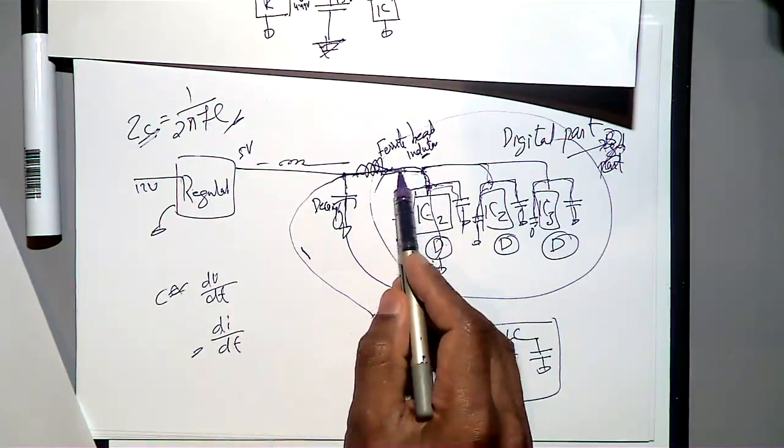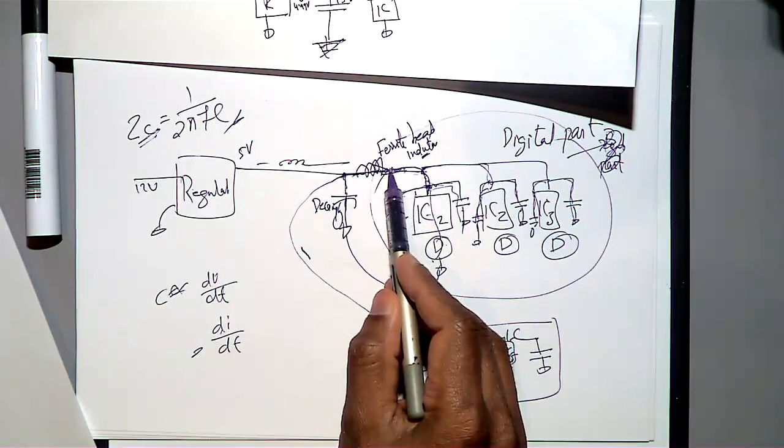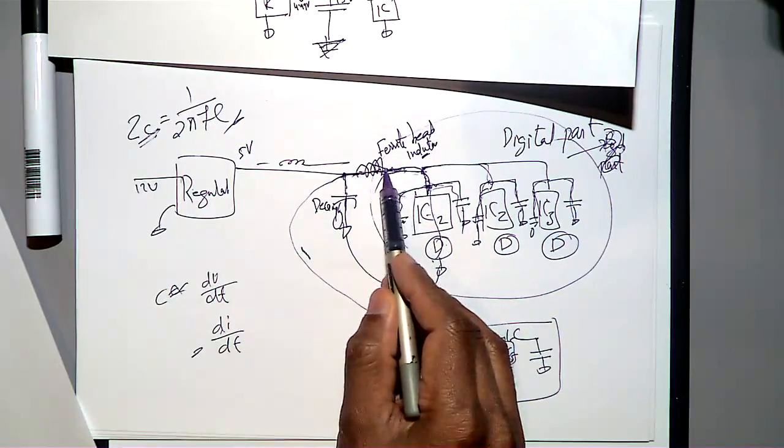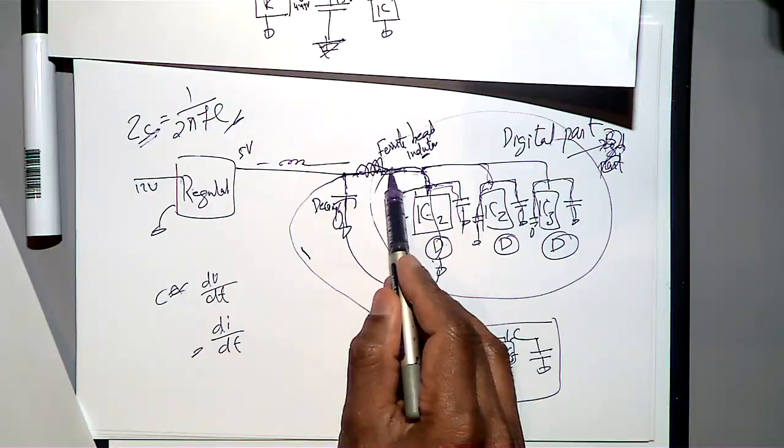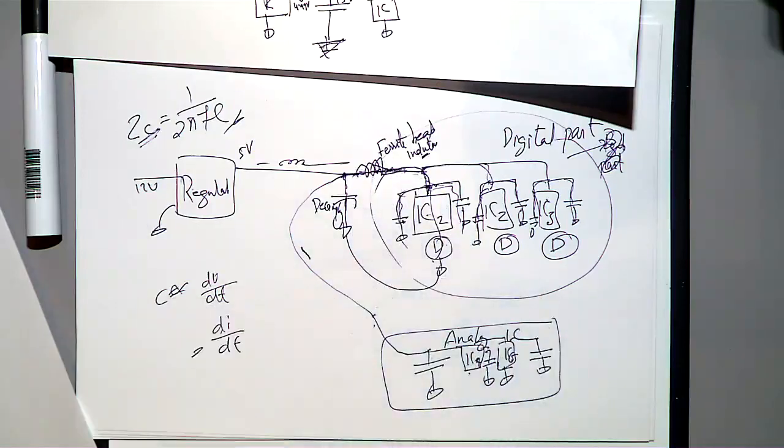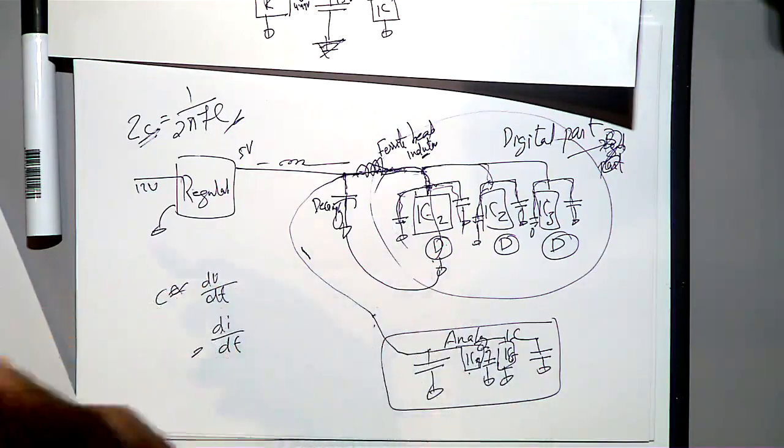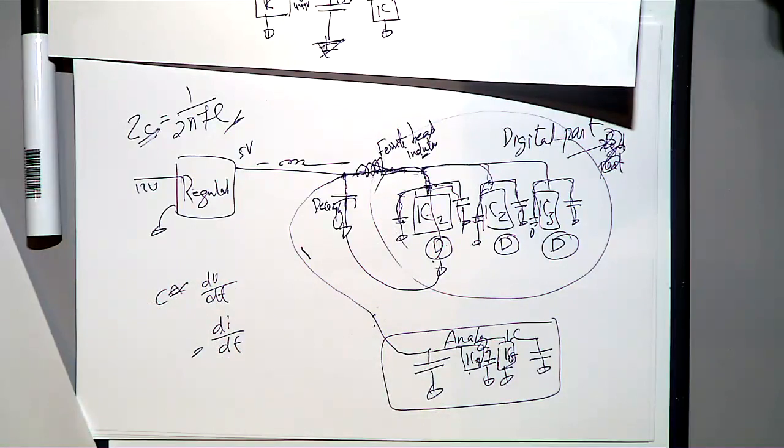So when there is a lot of noise, what will happen? The inductor will not pass it through. But if it is DC current, the inductor will be a short. But if you got some noises, the inductor will block it. It's just the opposite of a capacitor. If you got some variation, the capacitor will bypass it, because a capacitor blocks DC and passes AC, the noise, the variation. An inductor shorts DC, acting just opposite of a capacitor, and the noises and variations, it will block.